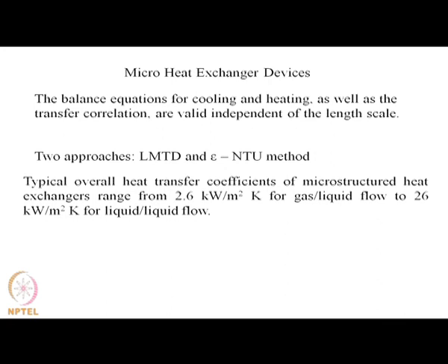When we design a micro heat exchanger device, we have already covered the balance equations for cooling, for heating, and the transfer correlations, mostly assuming laminar flow, and we know that these expressions are valid independent of the length scale. So, these expressions can be used for microchannels as well. Now, there are obviously two different approaches, the LMTD method and the epsilon-NTU method, while designing a heat exchanger, and any of these methods can be followed depending on the situation at hand.